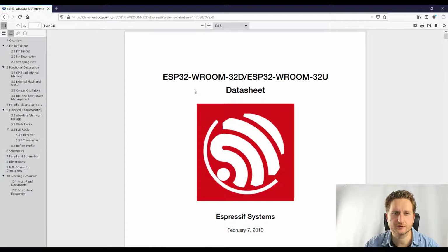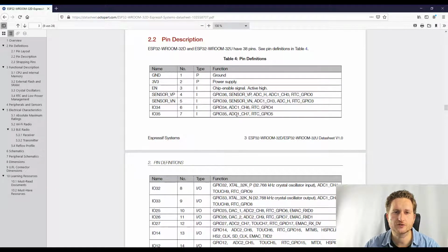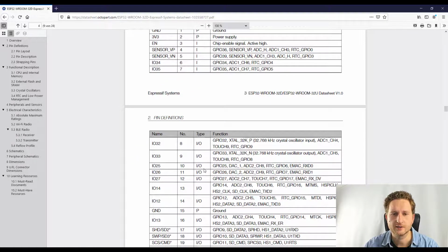And from there you get a description, the so-called pin description, where you see all the existing pins on this device with all its net names and its functionality description right here. And you see what kind of type the defined pin is: a power pin, an input pin, or I/O or something like that. We will create this symbol for the ESP32 right now.